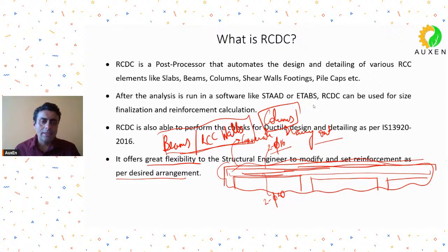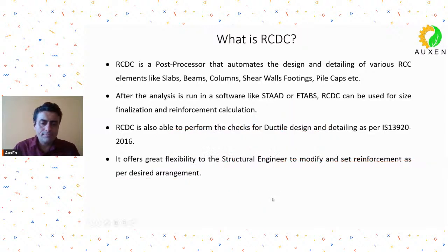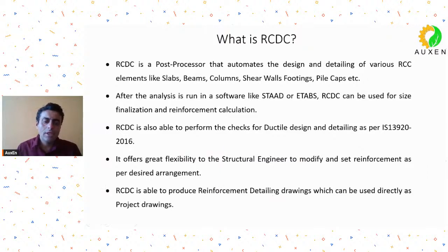In RCDC, that process is very easy, and at a click of a button you can actually set the reinforcement, do the design checking for that reinforcement, and then once you are happy with that reinforcement, you can even generate the drawings as per that arrangement. Not only drawings, you can also generate the BOQ as per that arrangement.